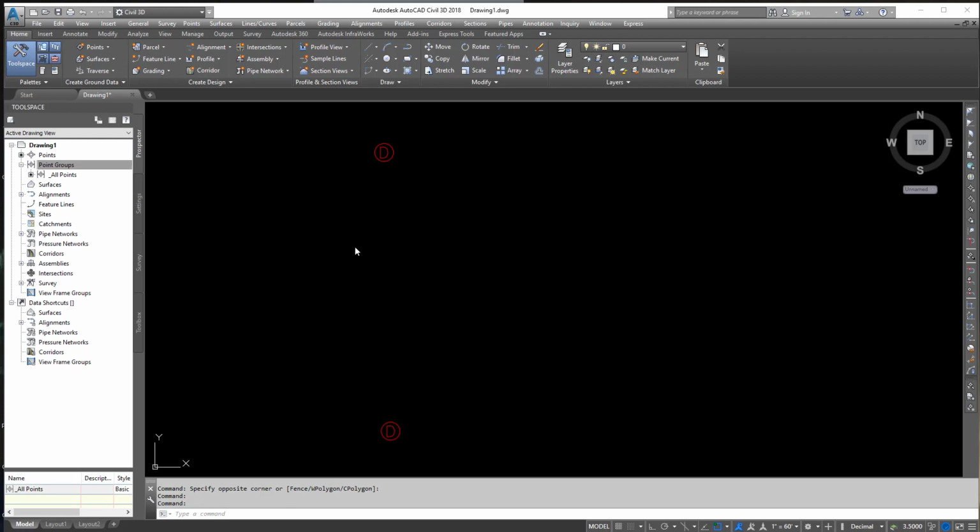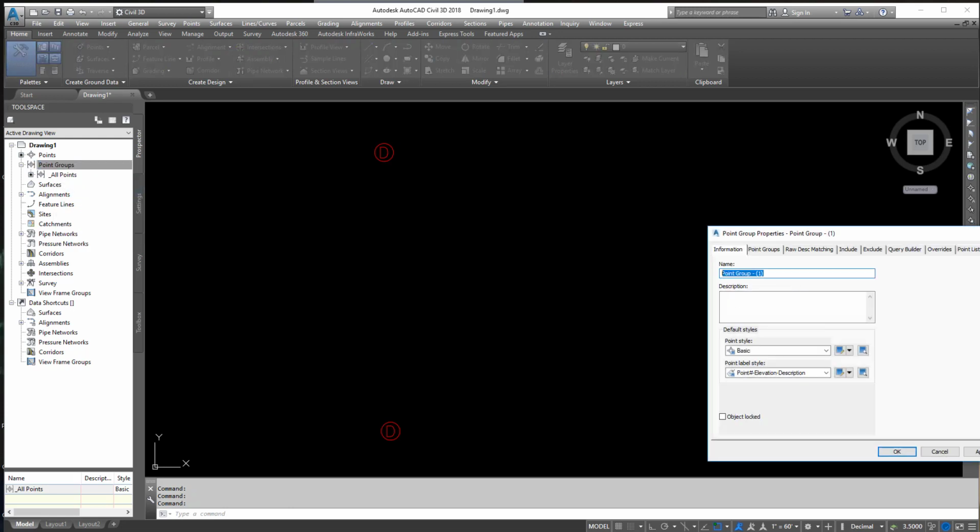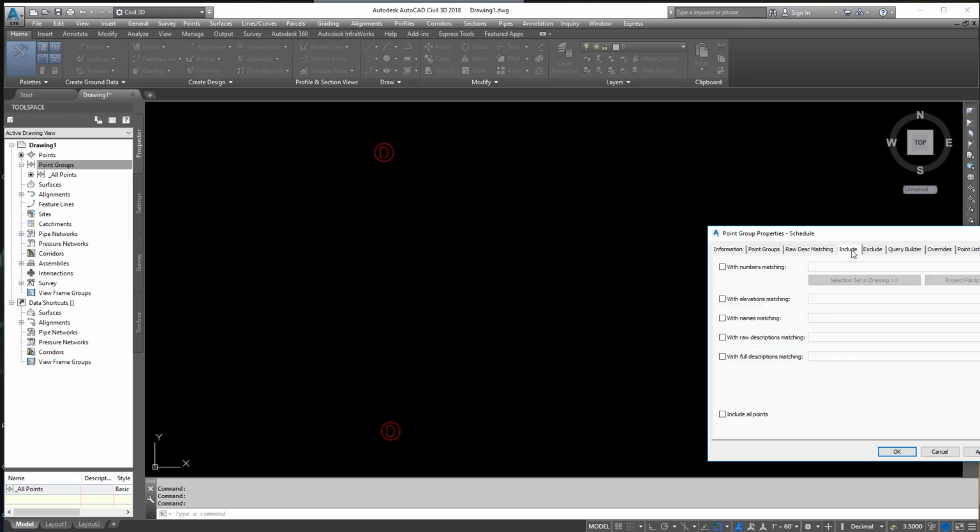So first things first, let's create a point group. We're going to come over here and create a brand new point group, and I usually just call it schedule. So we're going to call it schedule real quick here. And then we're going to include point descriptions matching all of your utilities. So if you have catch basins, sanitary manholes, or storm manholes, in this case is what I'm going to be doing, you've got to put all your descriptions in here.